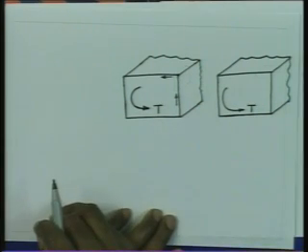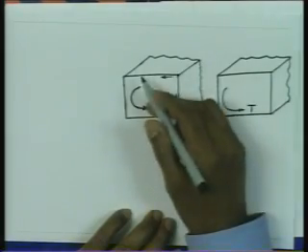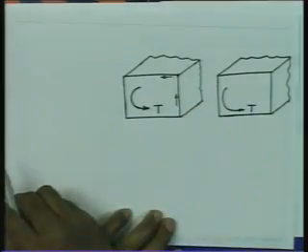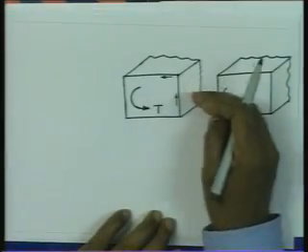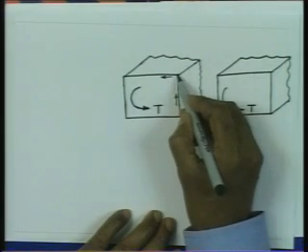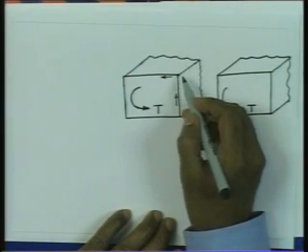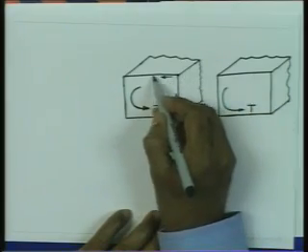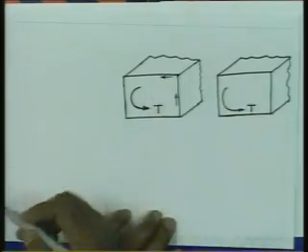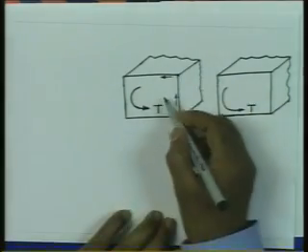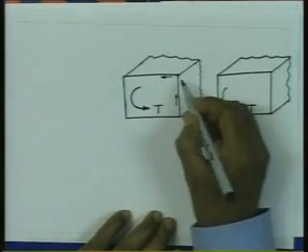Now, I would like to give you the answer from the consideration of the membrane analogy. Then, if you now think of the membrane attached to this boundary and it is inflated from inside, the boundary deflection of the membrane is going to be 0 here, boundary deflection of the membrane will be 0 there in the direction out of the cross section.